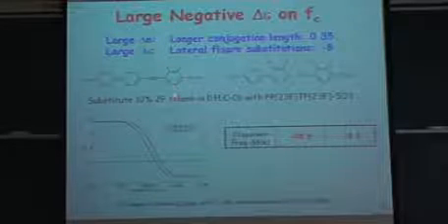And now it's our work. From the negative liquid crystal side, we change the structure. This structure has a delta epsilon of -4, and this one is -8. The dielectric anisotropy of the DFLC is a linear add-up of the negative and positive parts.